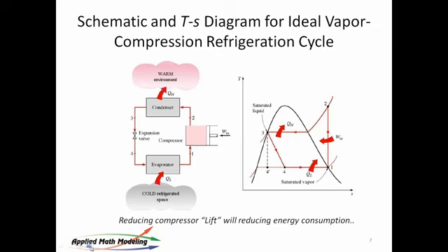So if we take a look at a simple cooling system, this is one that's a fairly good illustration that I looked at. They operate on the idea of phase change. And so this is a simple little circuit here that shows how these work. Generally, you have a medium that changes phase, and when you compress it with mechanical shaft power, the medium gets hot, and then you dump it to the atmosphere through some kind of condenser. Then, because you've dumped the heat, it's under high pressure on this side because you've pumped it up, and as it goes through an expansion valve, the temperature drops and it gets cold.